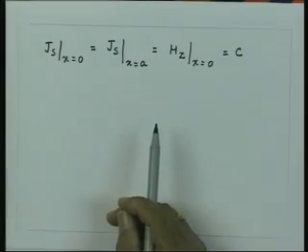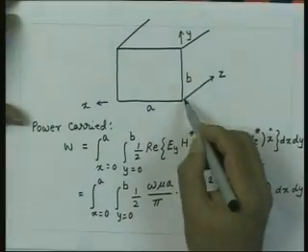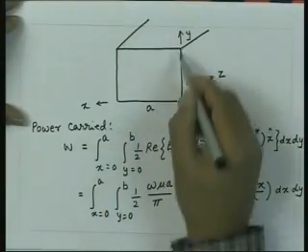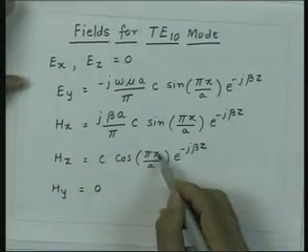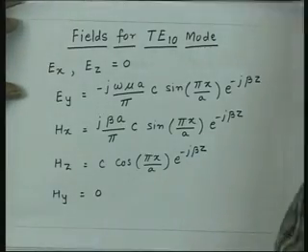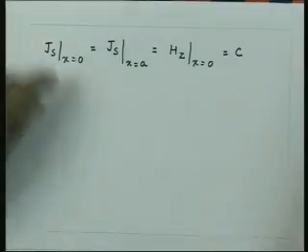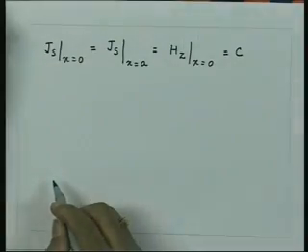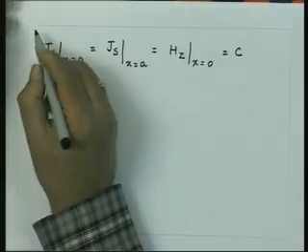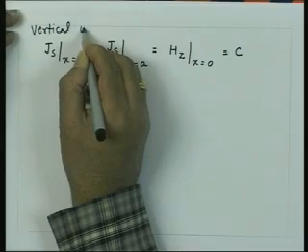So first let us calculate this loss for the side walls, which is this wall, for which we will have these two walls and for which the magnetic field is given by this. So x equal to a gives me the current in this, which is not varying as a function of y. On this wall also I can calculate from here the current which is not varying as a function of y. So these are the currents which are on the vertical walls.